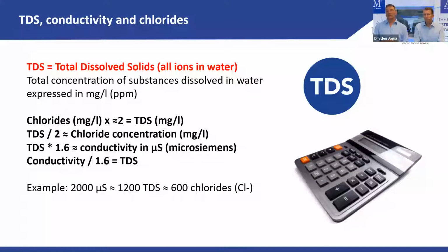And actually, it's really this conductivity that you can measure easily. These are hand meters, which cost, I don't know, 20 euros, that you can put in the water and measure the conductivity. This is expressed in microsiemens. Yeah, microsiemens. It's basically an electric current.